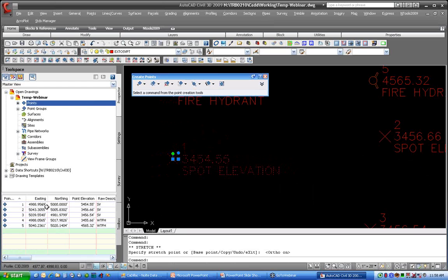One of the things I want you to notice is it modified the easting on the fly. So you really have to watch now, because these objects in the drawing are my point data. If I accidentally move them with grip edit and place them in a different location, they will change their coordinates, and that is now what the coordinate of that point is. It's not like I have the COGO point database where I can do the check points, update drawings like you do in Land Desktop. If I mess them up here, I need to go back to my original data and re-import them.